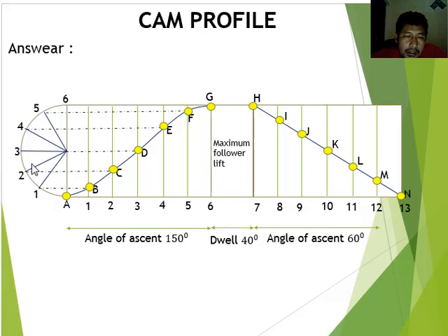And for the second, you strike a line to the right for point 2, and the intersection with number 2 part of the cam motion, you can draw as point C. Number 3 part for the semicircle, strike a line to the 3 part for the cam, and you have the D point. This is also the same for the 4, 5 and 6 parts between the semicircle and the cam motion.